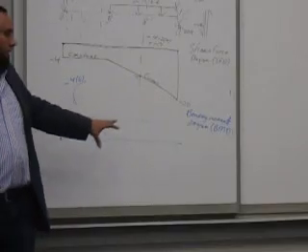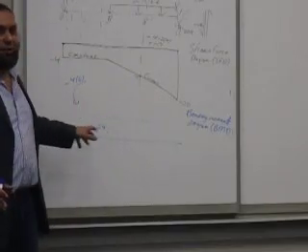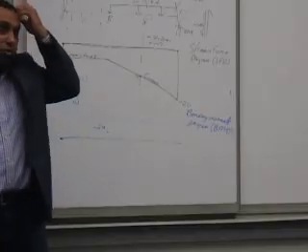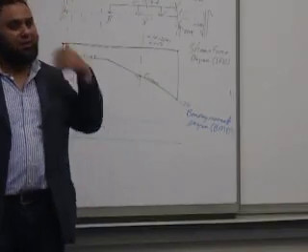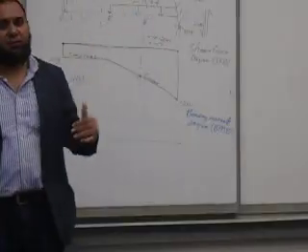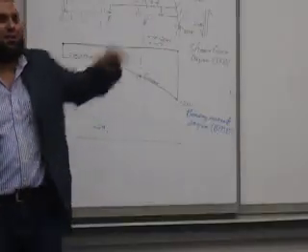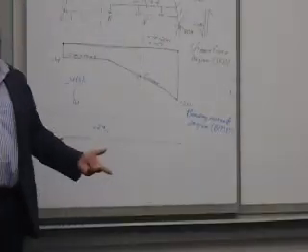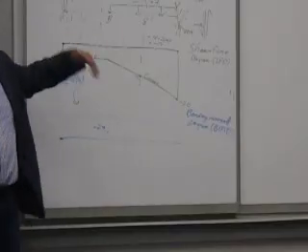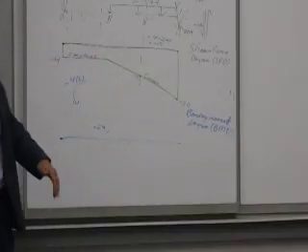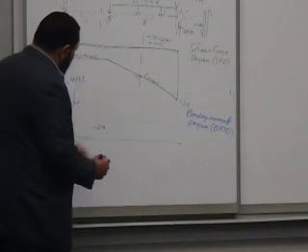Okay? So again, why do we do that? Because we do mainly reinforced concrete design, and we need to imagine where I will place my steel. So I'm always placing the steel in the direction of the bending moment. So this is why we are doing it this way. The negative is up, the positive is down. Okay? Right. So this is negative 24.